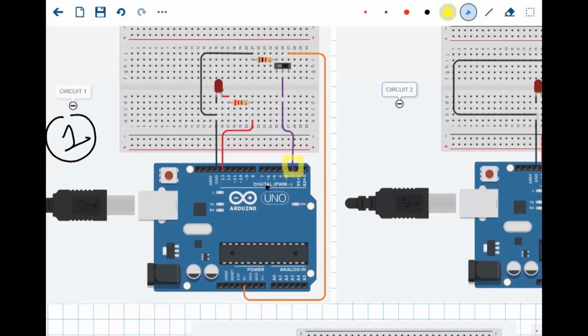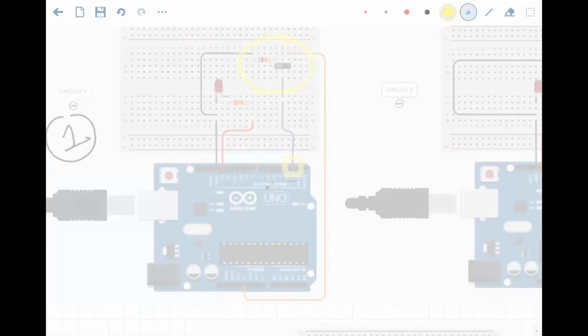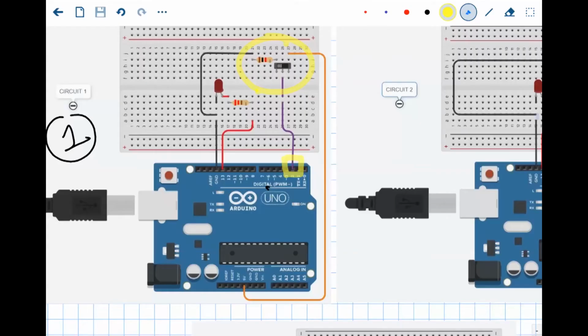Now, because Arduino does not have a dedicated input system, it is a flexible port. Arduino prefers to have a pull down system. That means if you see over here, commonly our on off system is either connected or not connected. For Arduino to have an input of 0, the signal or the input needs to drop down to the ground or 0. That is why we have a pull down resistor where when the input is not 1, it is forced down to 0. If it is kept floating, there are jitters and the program doesn't work properly. So Arduino requires that you drop a pin down to 0 to make it a 0.